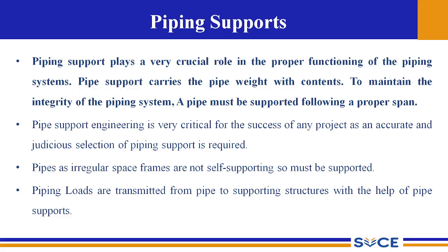So pipes as irregular space frames are not self-supporting. If you have long pipe runs, they are not self-supporting in nature. So we have to provide adequate support systems or arrangements to be installed in a proper fashion so that we avoid the failure of the pipeline.